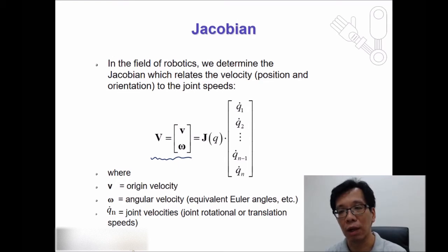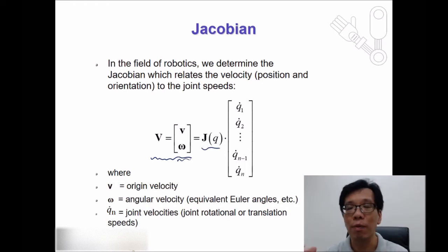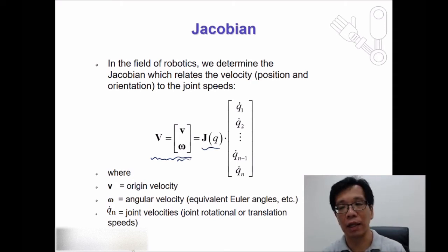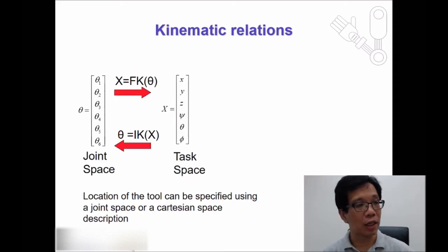And in order to find the change in velocity, we need a Jacobian matrix multiplied by all the inputs. The inputs over here may be multiple variables because we might have multiple joints. Individual joints have their own angle, their own distance. So combining everything together, we can find my velocity and angular velocity. That's the basic idea.